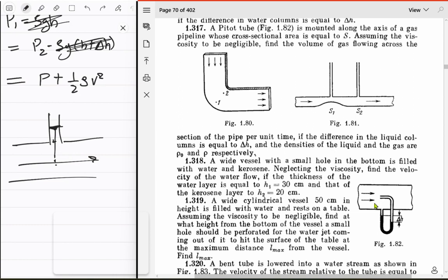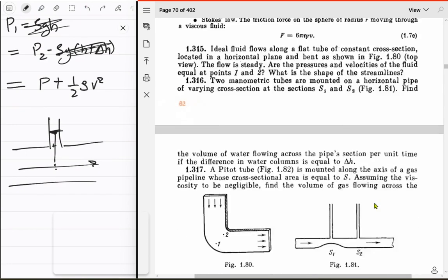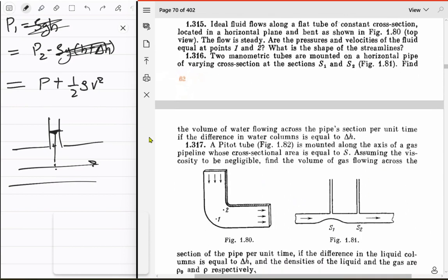That's a problem, because now you can't apply Bernoulli's equation everywhere. You can only apply it in the central region where there are low viscous forces. But that means that our manometer thing that we did last time, you can't get the result from Bernoulli's equation. So how do we know that the pressure it measures is the hydrostatic pressure? This is not working. How do we know that pressure it measures is in fact the hydrostatic pressure?